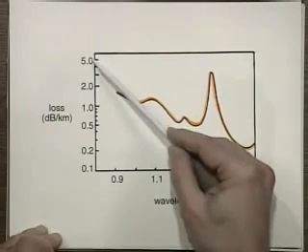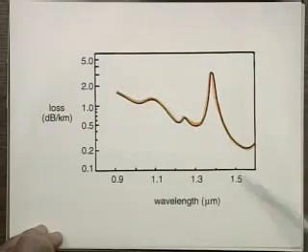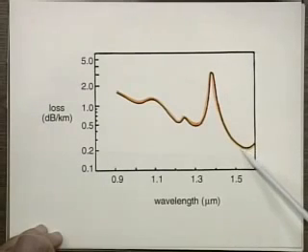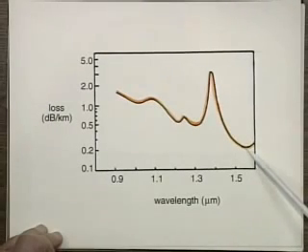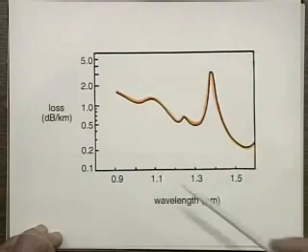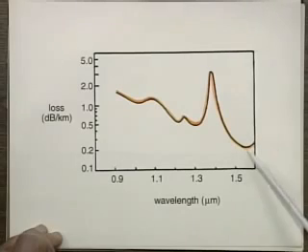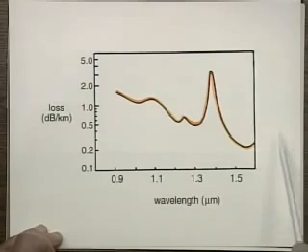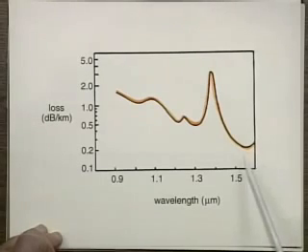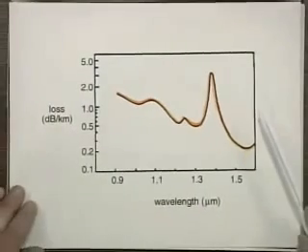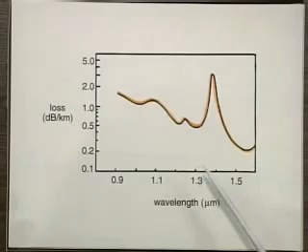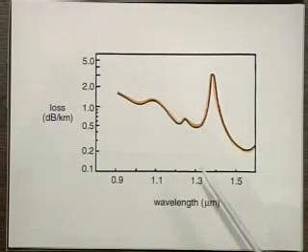So you're boxed in on one side by Rayleigh scattering. The other side, going up, is the material absorption, and that's why you have the lowest loss around here. And that's about the best you can do. If you want to reduce this loss from, let's say, 0.1 or 0.2 dB per kilometer, then you have to use other materials, materials whose material absorption is further into the infrared. So I'm afraid we're not going to get into the visible and have low loss, because of the Rayleigh scattering.